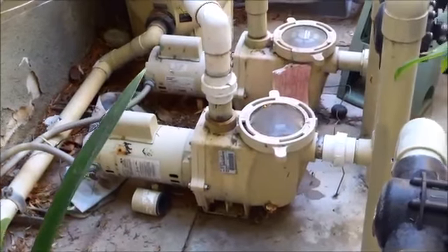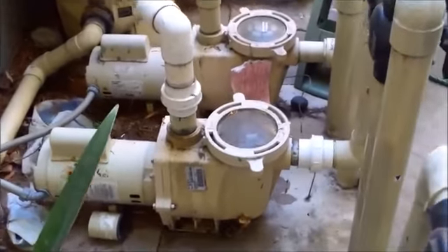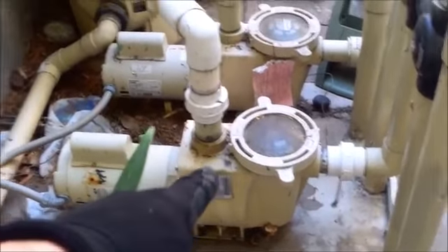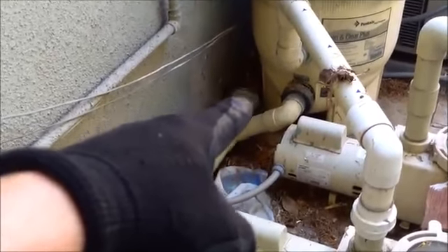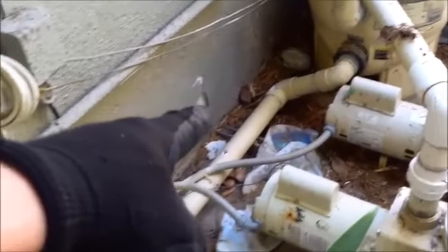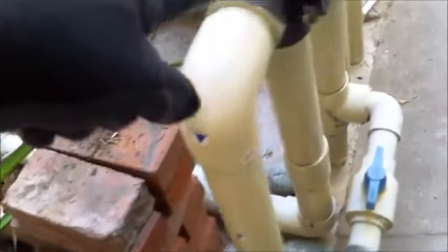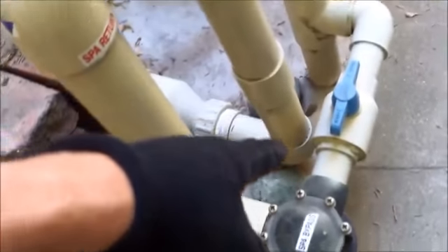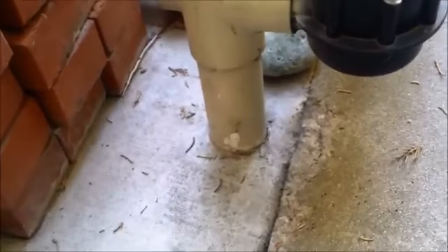It can be a little confusing and overwhelming with all these valves and lines. Basically, you can trace your system at the pump here going into the filter, and you can trace the return coming out. You see the filter's marked outlet. You can trace the plumbing here going into the heater unit, and then back out the heater, back over here, back through this area, and back into the pool, the return area of the pool, into the return lines, down into the cement, into the pool.